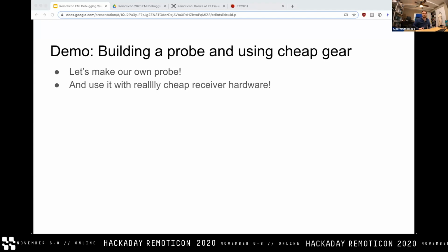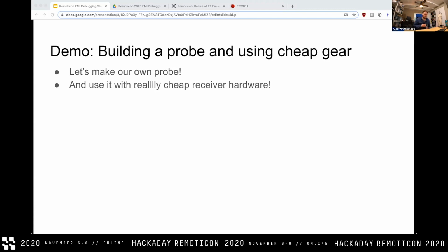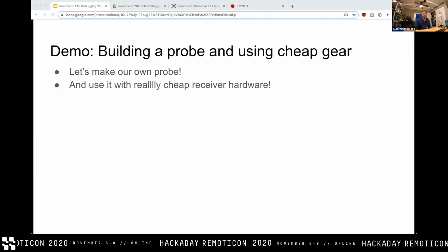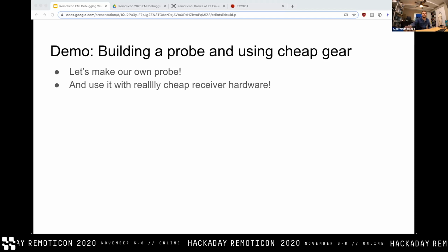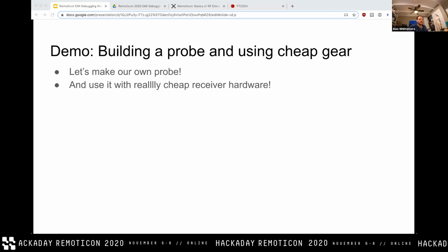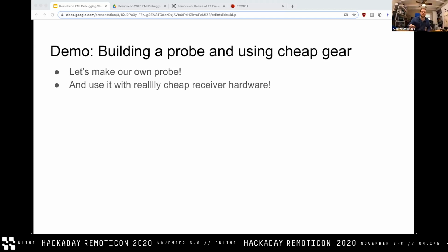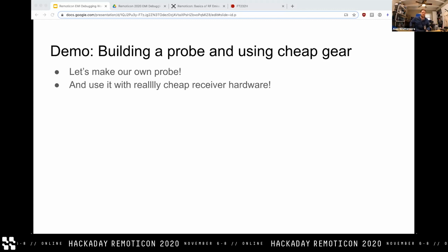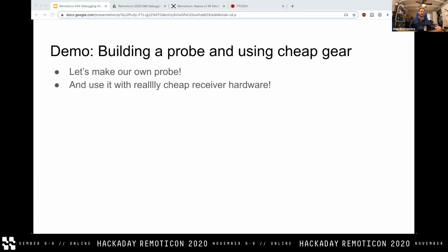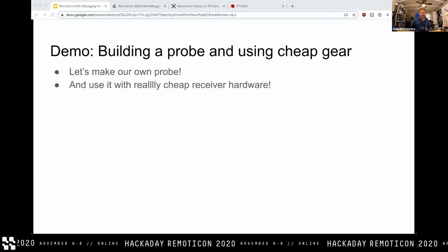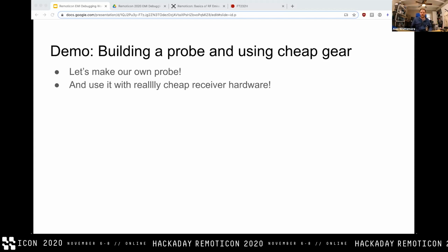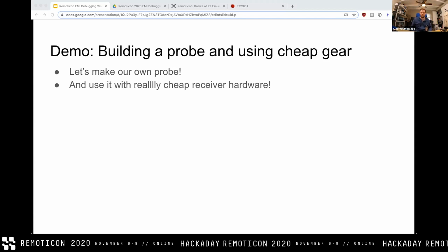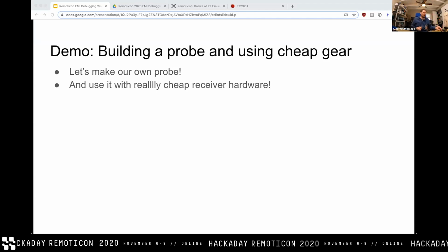So in that design, it was the LAN 9512, right? The LAN 9512 was radiating all of this 250 megahertz noise. It's not enough to just wave your magic wand over the LAN 9512 and say, huh, it's the LAN 9512 making 250 megahertz. There's no thing in the data sheet for that part that says, this part will radiate 250 megahertz like a banshee off of this pin, figure it out. They don't offer you that kind of guidance.